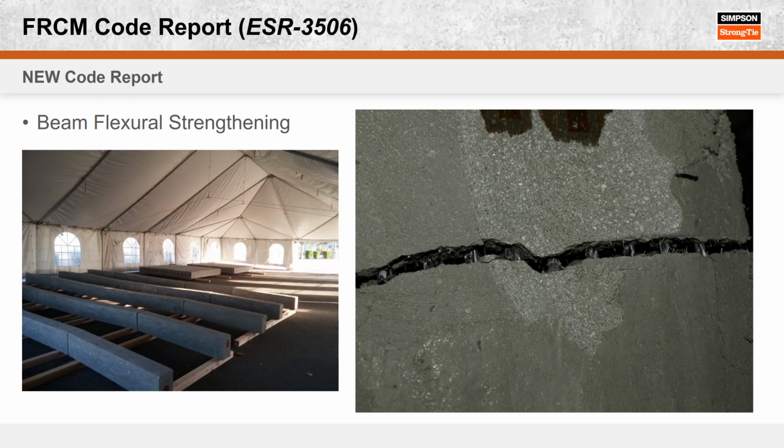Well, remember this is FRCM too, right? So we need a CSP 6 to 9, so very rough. You can't get that with a grinder. Oh, right. To get that with a grinder, you have to gouge, and that's not the way to do it. So pretty much for FRCM, you need a walk-behind scabbler or something that makes a really rough surface. So grinding would not work on this. Good point.